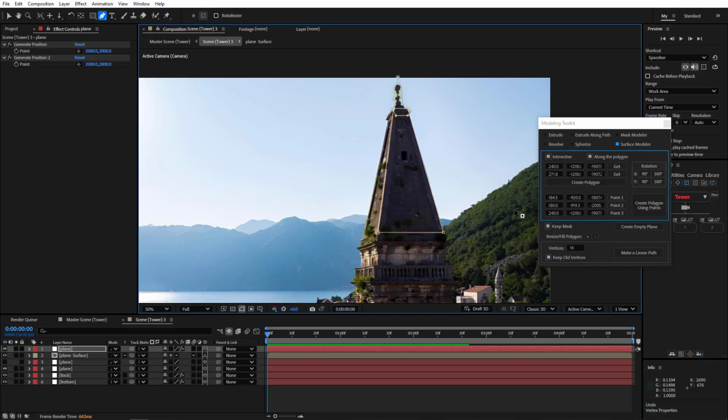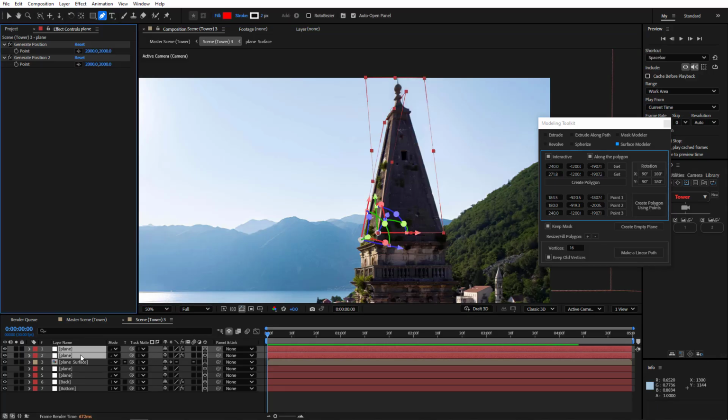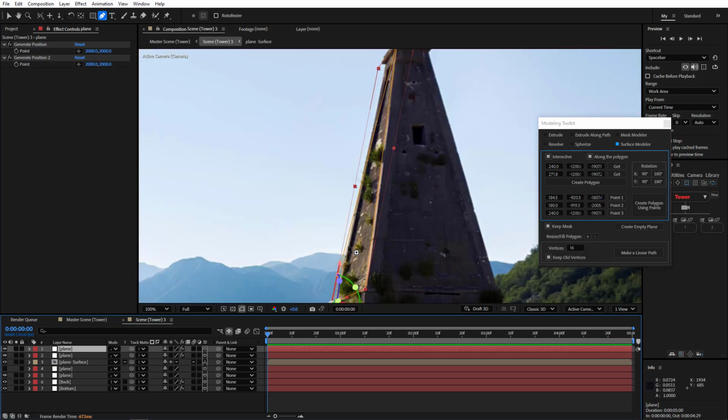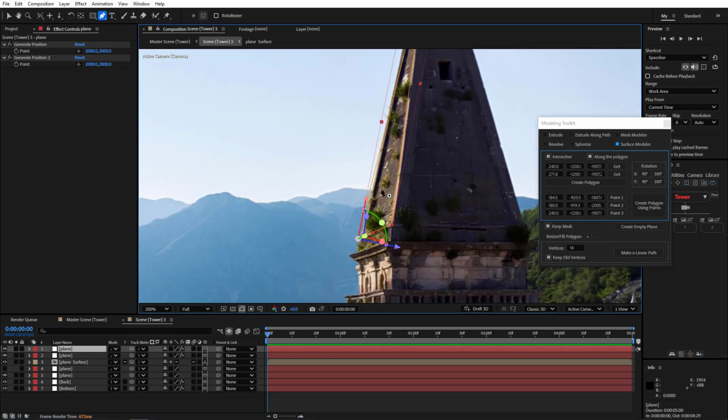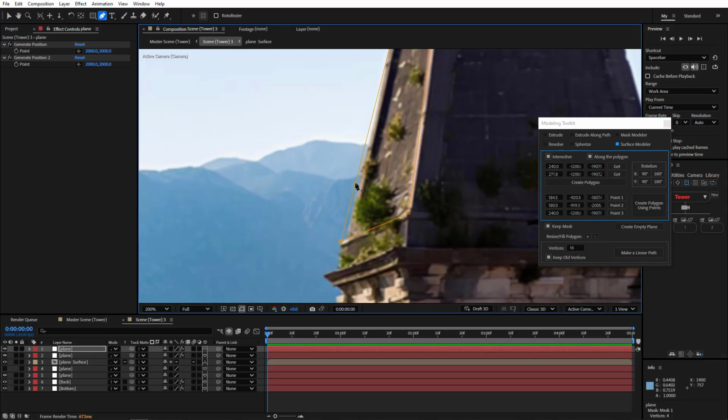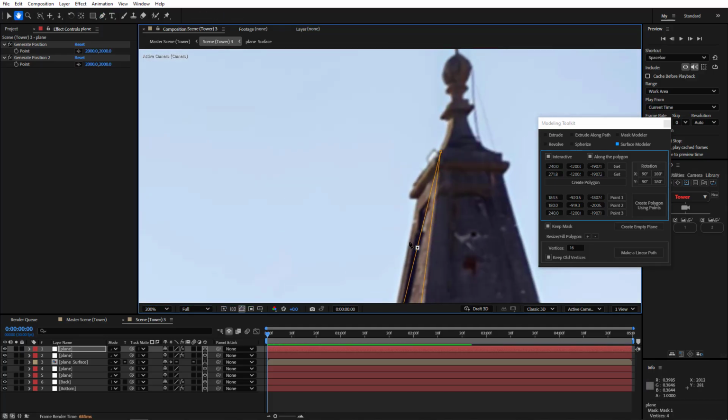And now it will not be difficult for us to create this part of the surface. Just click this Create Polygon using Points button. And that's it. We get a triangle since we had 3 points. But the important thing is that it touches the other parts at all 3 points. All that remains is to add new vertices and adjust the surface along the contour.